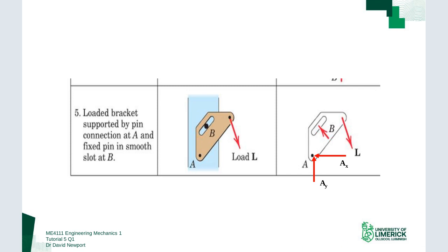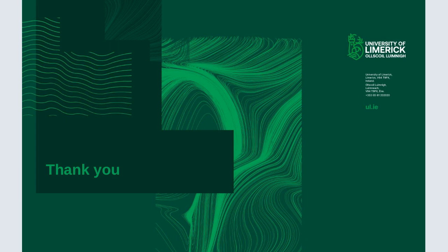Okay. So again, just practice free body diagrams. Make sure that you're comfortable with them. You should always indicate in them your coordinate system also, so that it's obvious what coordinate system you're using. And just bear in mind that the whole idea of the FBD is that you're basing your solution off it. It's your model of it. So it's your presentation of how you're going to solve the problem.